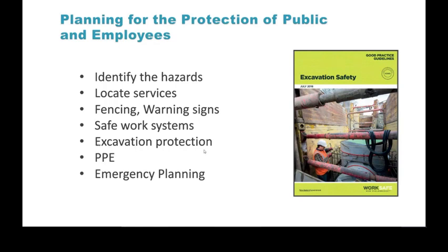Protecting your excavation. So in this case, they've got some hydraulic shoring this guy's standing within. So that's protecting him from trench collapse because he's pretty deep down there doing that work. PPE, high vis, steel cap boots, hard hat would be your bare minimum.